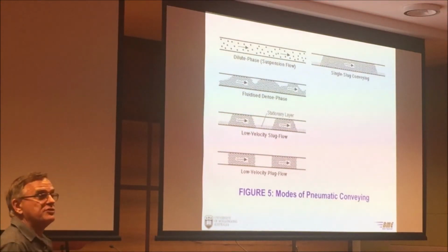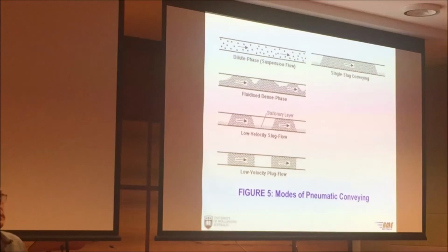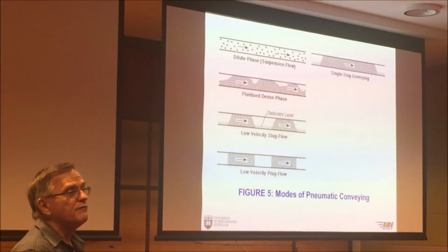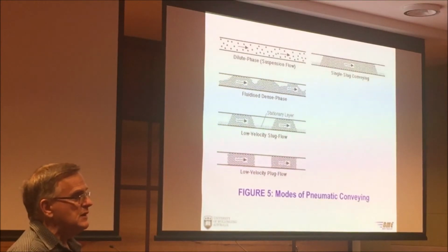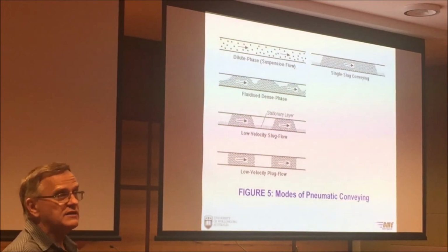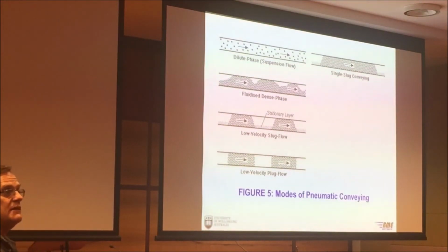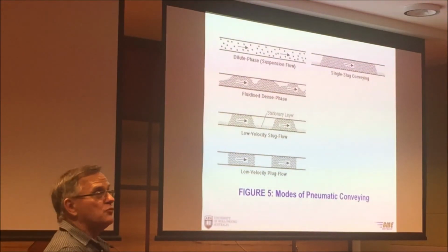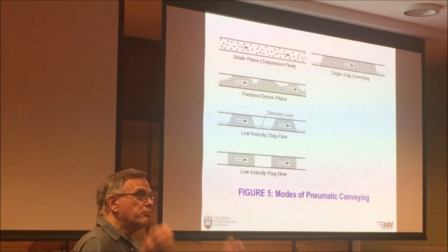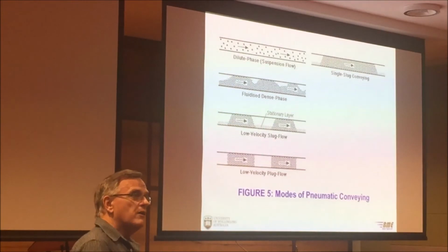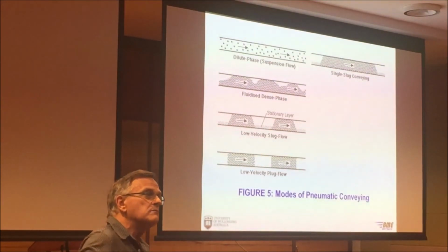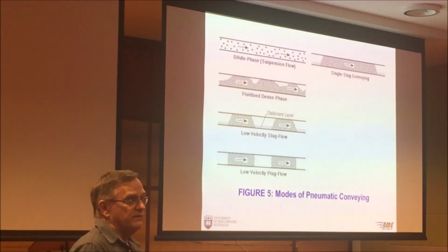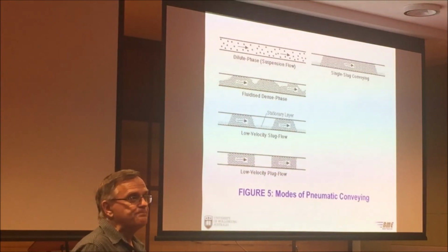My first consulting project was in 1983, I remember, and it was single slug conveying of diamond ore aggregate for the Argyle diamond mines. And we designed about 12 pneumatic conveying systems, took about 3 million in the deep end, and all those systems were installed. We put pressure vessels in with wear liners, replaceable wear liners. So, 3-inch quartz rock going through a pipe pneumatically is unheard of, but we did it.